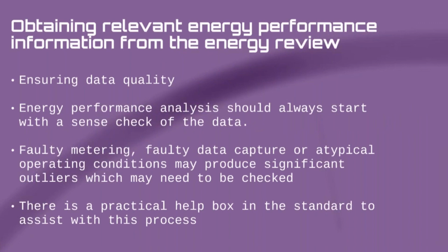So on to ensuring data quality. Energy performance analysis should always start with a sense check of the data. It is tempting when you've had information collected automatically and put into spreadsheets. It all looks very very tidy and neat and ready to use. You do need to check that the data you're using is reliable. Faulty metering, faulty data capture, unusual operating conditions may produce significant outliers which would need to be checked. You know, they may be real, but they may be false.